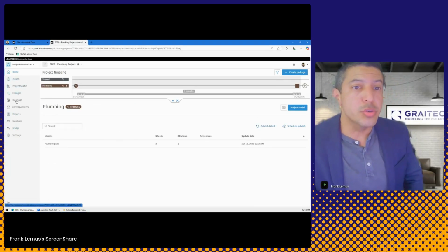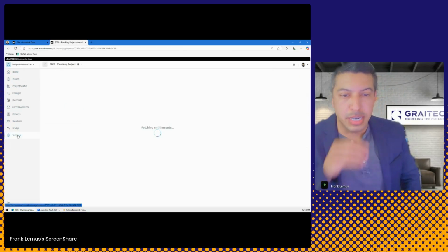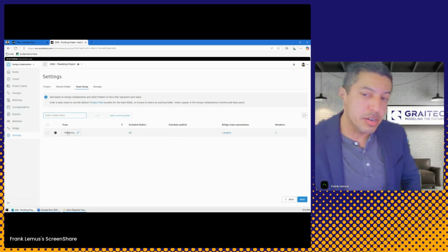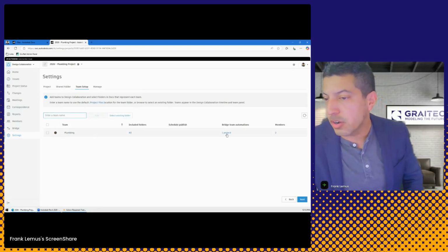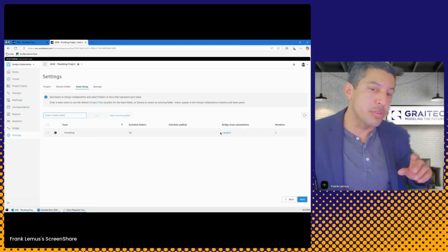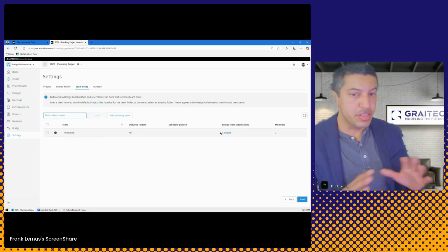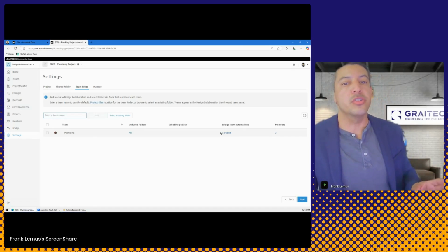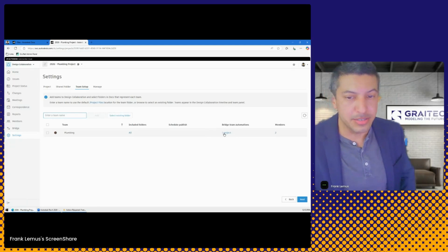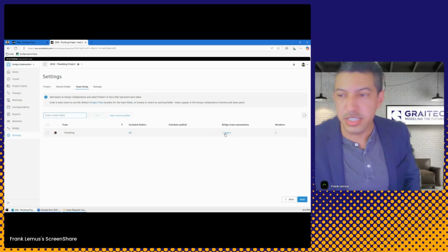So to do it, what you do is you're going to go to the design collaboration module, and you're going to go down to the settings. Now, I'm trying to share the packaged files from the plumbing team over to the architecture team, and I do that over here. So instead of going to the docs environment and sharing a particular folder, which is a very legal maneuver, but it's not good if you're trying to share the packaged files, because this is more automated for that. Okay, I'll show us the other way in just a second.